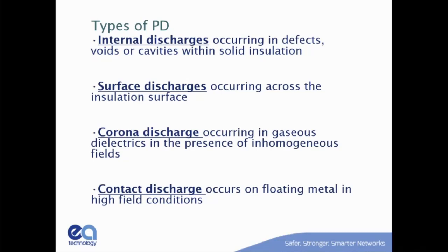Internal discharge is where it's occurring entirely inside the insulation. So like that air bubble I showed in the previous picture, or maybe you've got insulation molded around a conductor and it's delaminated somewhere in the middle. Basically anywhere where there isn't access to air. And these are really troublesome because you can look at it, you can inspect it. Let's say you get a contract that maintains a switchgear, and you take it all apart and you clean it and you inspect it and you do a Megger test and you do a withstand test and you put it back in service.